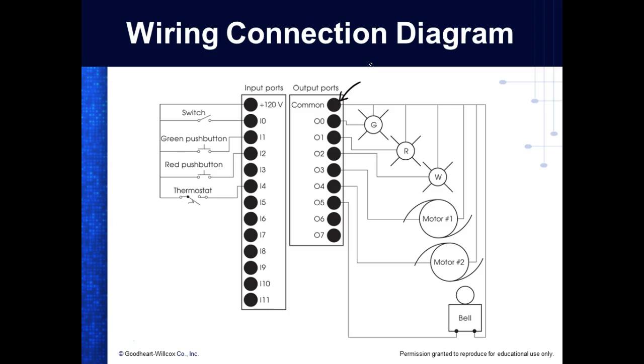And why? Because 24 volts is below what is called the lethal voltage. NFPA 70E is the standard. If y'all haven't heard about that, if you get in the industry, I guarantee you will. It's a safety standard, and what they say is anything above 50 volts is considered to be lethal. It doesn't mean you can't get killed under 50 volts. It's just highly unlikely, right?